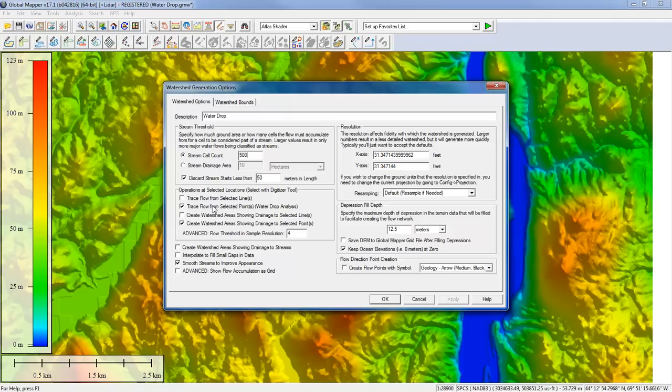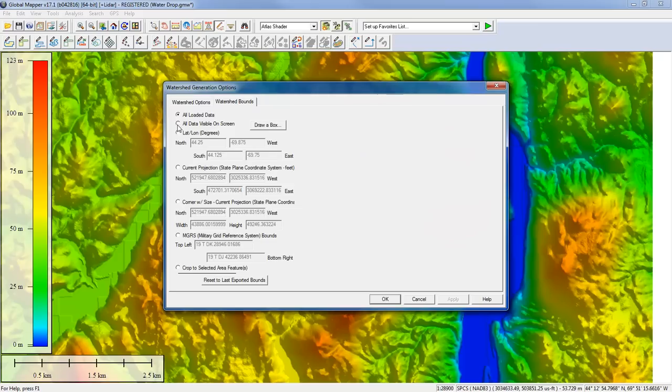You'll notice a couple of checkboxes that are checked here by default, given that I'd selected a point. The one that we're going to use in this case is the flow from analysis. We're going to uncheck the flow to option and readdress that in the next scenario. This is all we really need to establish in this case. We're creating a new layer so we can name it accordingly. We'll click OK. Actually, I'm going to limit the extent before I do that.